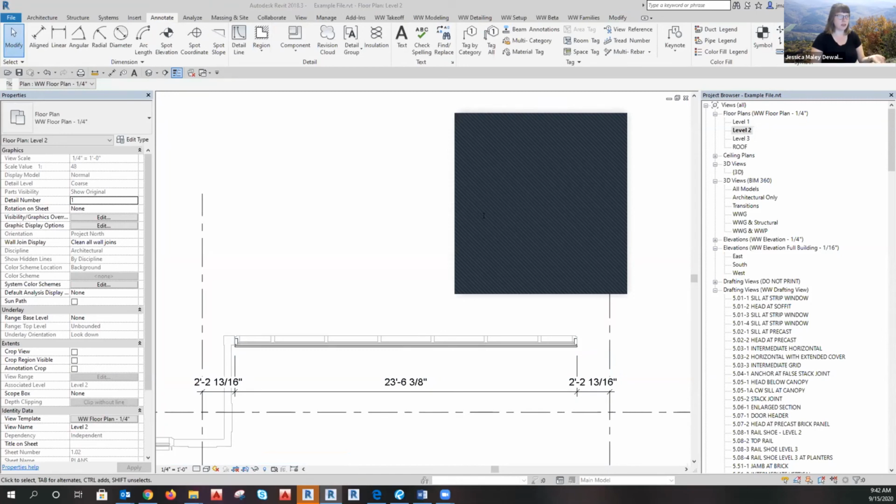Where would you check the architect offset? That's in your contract documents, so your architecturals, like your PDF documents, are always going to rule over the model. So you can't just copy straight from their model. You need to be looking in the PDF documents to verify the intent.